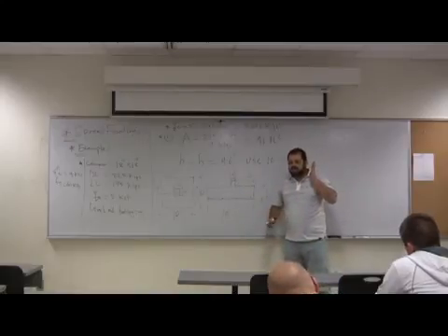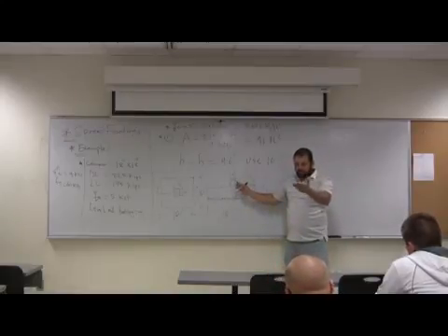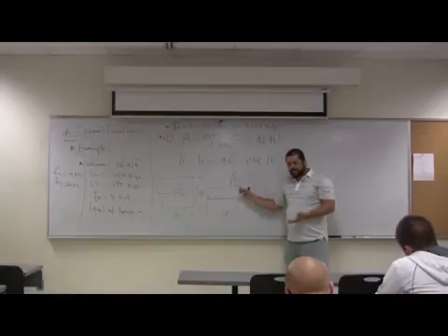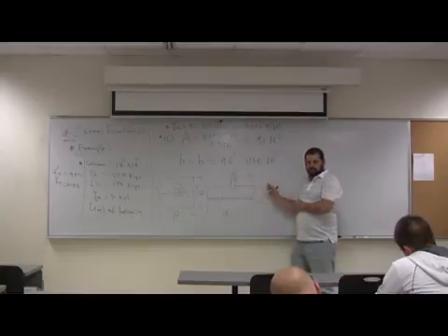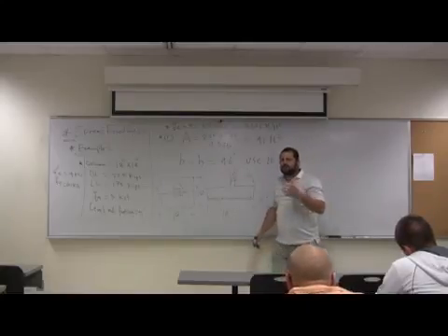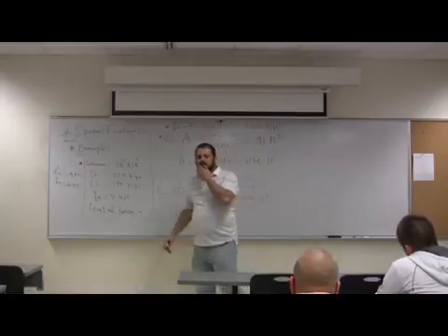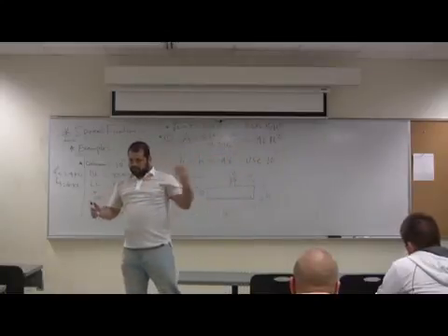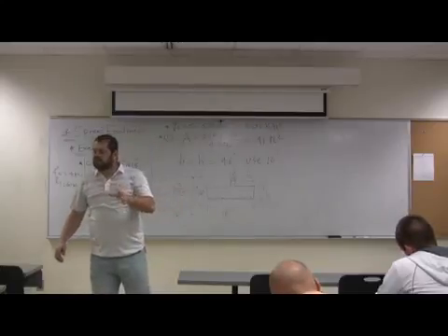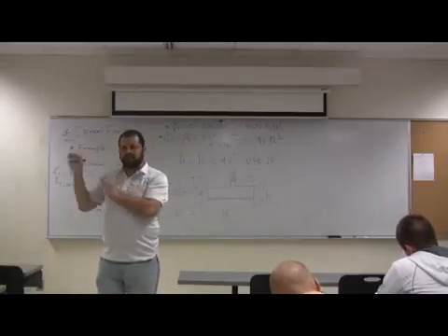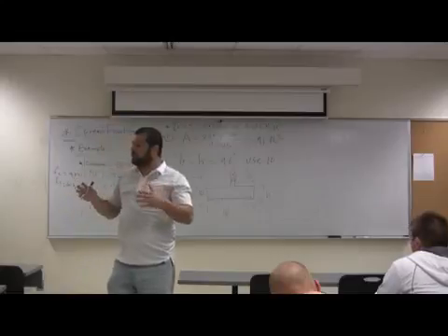We said the critical section for shear, I expect you to know, is at D from the face of the column. We don't have D. That shear that we deal with, at D from the face of the column, you know what they call it? They call it the one-way shear or the beam shear. It's like the shear in the beams.